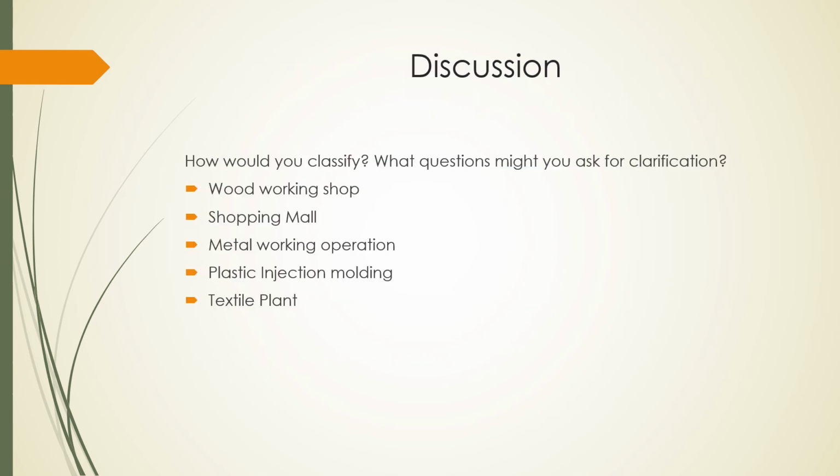So sometimes classifying these occupancies is simple, and sometimes it's not, and sometimes they're different occupancies depending on where you are within the space. So for instance, a woodworking shop's pretty straightforward. You're likely not looking at any kind of storage per se. You're looking at an extra hazard group 1 occupancy, fair amount of wood on site, scrapings, that sort of thing. Shopping malls, interesting, mercantile operation.